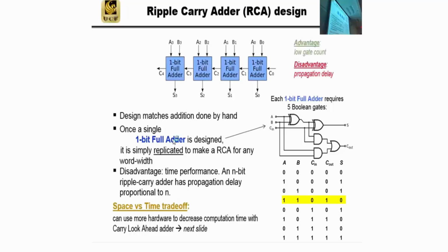which is, the output sum is 0, right? And what's the carry? 1. So that was one case where this is a 1. Is there any other case? Yes, speak up. A is 1 and C is always 1. Exactly. So you can have either one of these be 0 and an input carry of 1. You're going to have a carry propagate out.